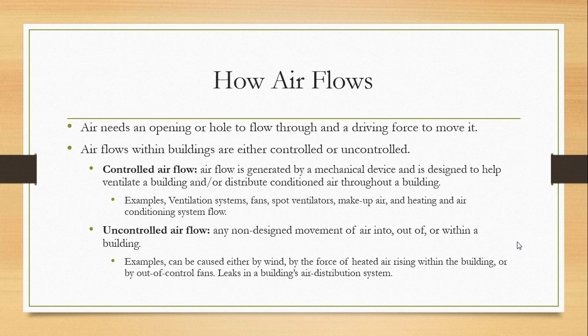So let's talk a bit more about air flows in the context of the building. So air needs an opening or a hole to flow through, and also it needs a driving force behind it in order to move it. So it needs a pathway and a driving force. The air flows within buildings are either controlled or uncontrolled. Examples of controlled airflow, they'll be generated by mechanical devices. For example, you have ventilation systems and fans within your building.